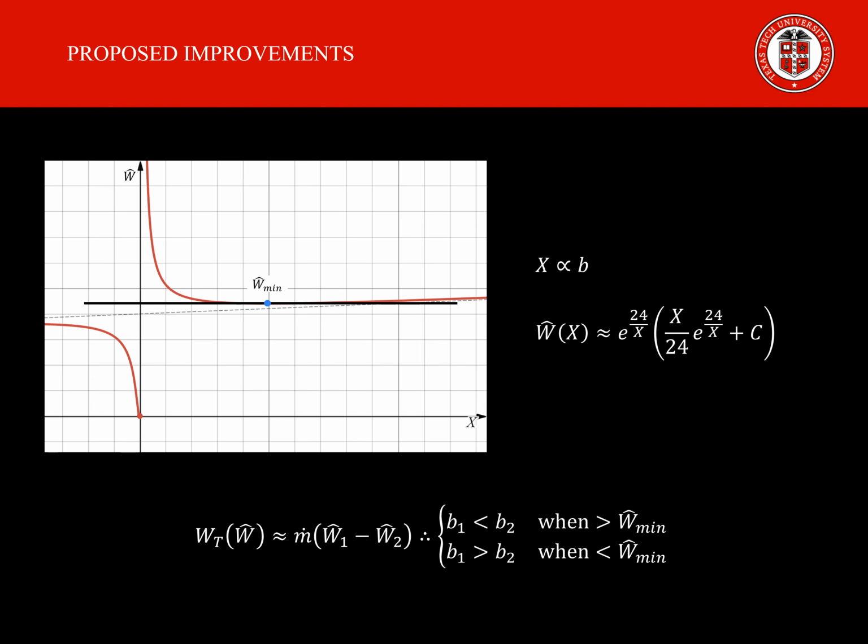To maximize work out, the inlet's relative velocity should be larger than the central orifice relative velocity. This can be achieved by designing disks that taper in thickness towards the shaft to allow for larger spacing near the exhaust, effectively reducing the exhaust's relative velocity and therefore producing more power.